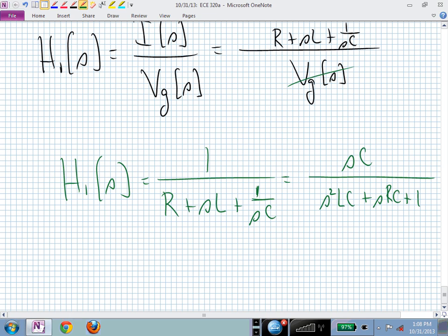If you didn't have a resistor, you would lose that middle term, and what would you have? You'd be right on the vertical axis, right on the imaginary axis, wouldn't you? And what happens when you have something right on the imaginary axis in terms of its stability? No decay. It just sits there and shakes, doesn't it? So you would have built an oscillator.